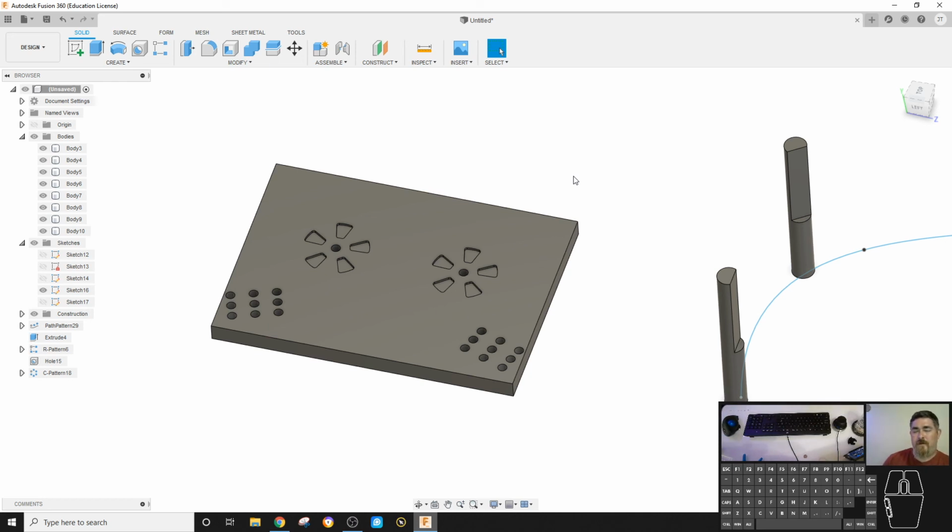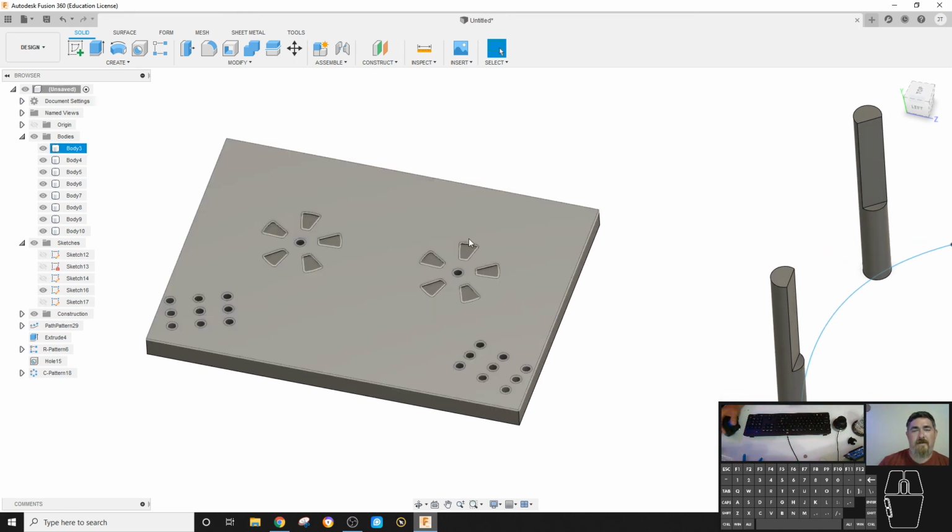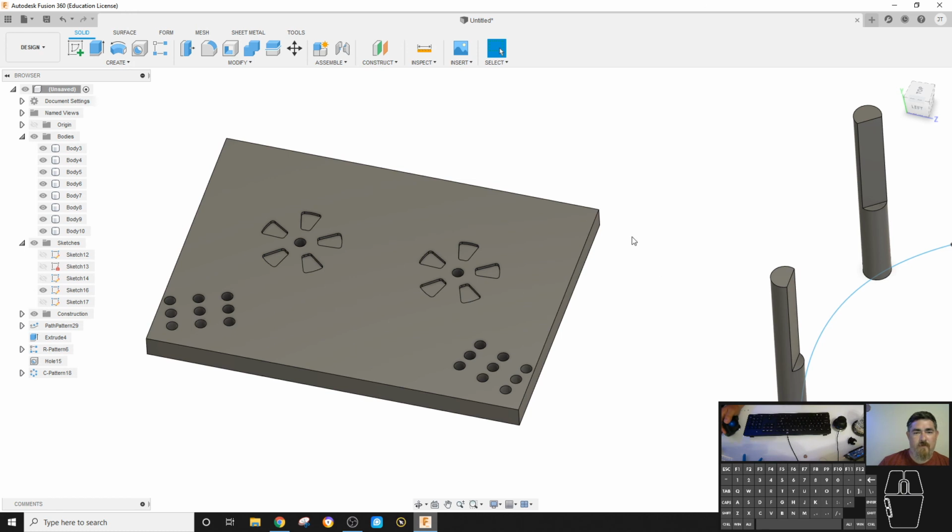If you're wanting to do things that are symmetric, don't do the work of doing it on both sides. Do half and then just mirror it over to make the other half. Same thing if you want things that are in a pattern, do one and then pattern it. Don't do the extra work of totally redefining it each time. That's a lot of work.